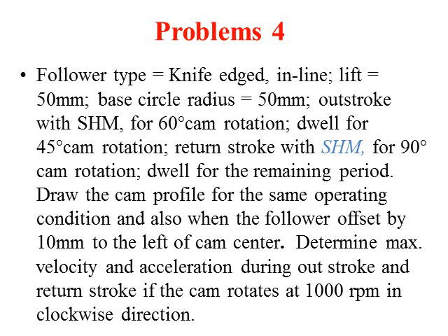Next, we need to draw the cam profile for the same operating condition, that is inline, and they also mention drawing the cam profile when the follower is offset by 10 mm to the left of the cam center. In the problems we solved earlier, the offset direction was not mentioned. When it is not mentioned, we assume it will be on the right side. But in this particular problem, they clearly mention the offset is 10 mm to the left of the cam center.